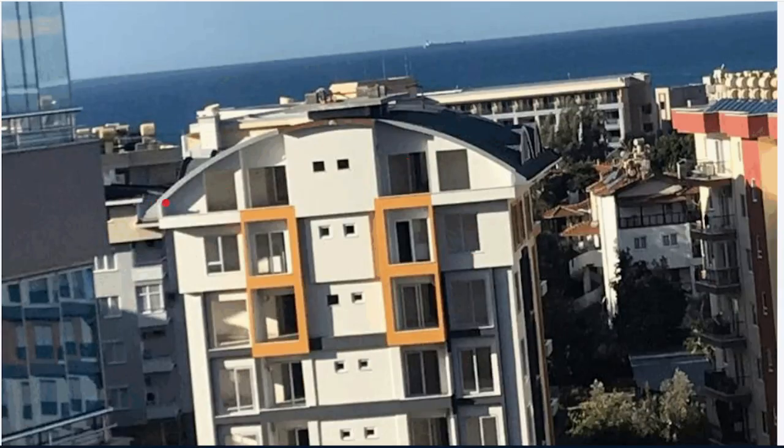So in the cylinder roof that you can see, the cylinder roof has been drawn. You can see that in order to distinguish the first duplex part from the second duplex, there should be at least some level difference, minimum 20 centimeters or maximum 80 centimeters, to distinguish the second part of the duplex floors.